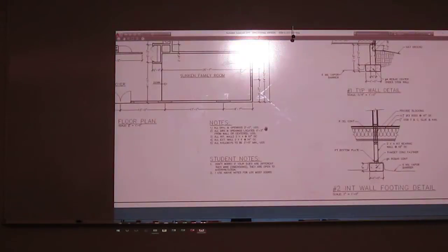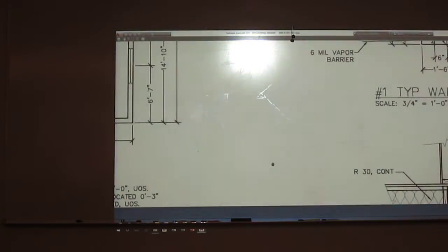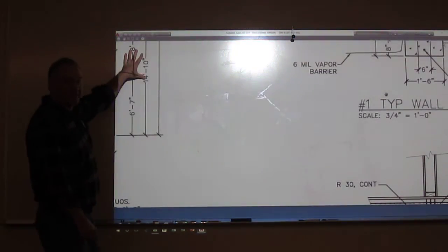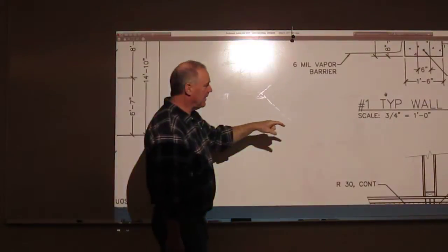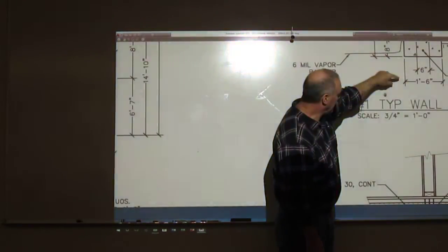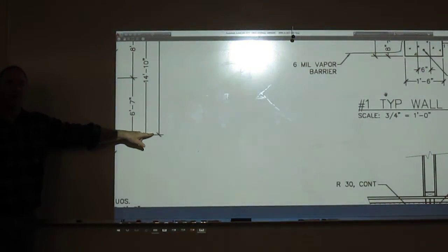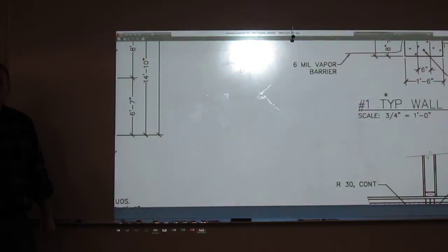Now, let me kind of zoom in over here where I can see both of these at the same time. And I think right here you can, up on the 3/4. So this one's printed with a DSF of 48, 1/4 inch to a foot. This one is printed at 3/4 to a foot, my DSF is 16. But is that slash mark the same as that slash mark? On the print? Yeah, they need to be the same. I want all that the same.